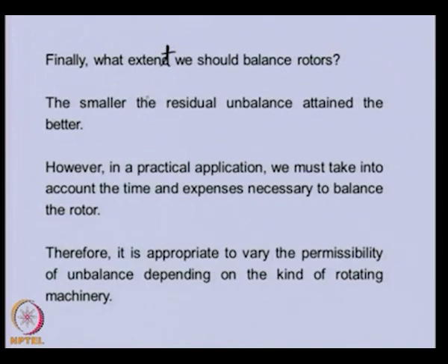The smaller the residual unbalance attained, the better. Best is if we can reduce the unbalance to a very small value, but however, in practical application we must take into account the time and expenses necessary to balance the rotor. That is very important in industry. Therefore, it is appropriate to vary the permissibility of unbalance depending upon the kind of rotating machinery.